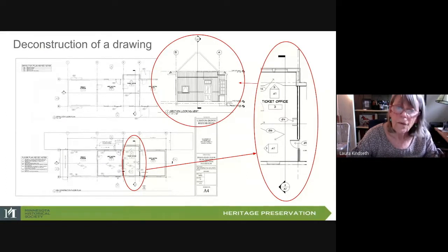And then the orientation of the section drawing that you're going to find is indicated by the direction of the arrow. So it will be facing west. And you'll also note there's a number in the arrow, which is 2 at the top, which indicates the drawing number at sheet A7. So you go to that sheet and find drawing number 2, and here is your section that you would find if you were to cut through the building.